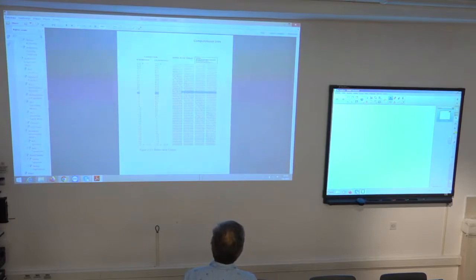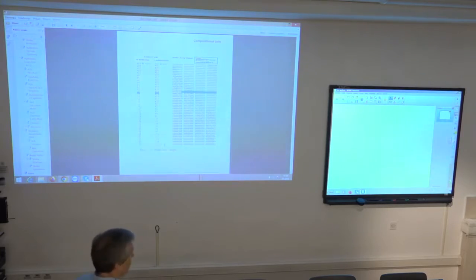Then it supports 128 shifts to the left or to the right. Of course, it doesn't make sense to shift something 128 times since the output register is only 32 bits wide. But nevertheless, the width of this register, SE, is 8 bits, so it is a two's complement value. Theoretically, it supports shifting left or right by 128 positions. Such huge dynamics of shifting doesn't make much sense, but it handles exceptions.